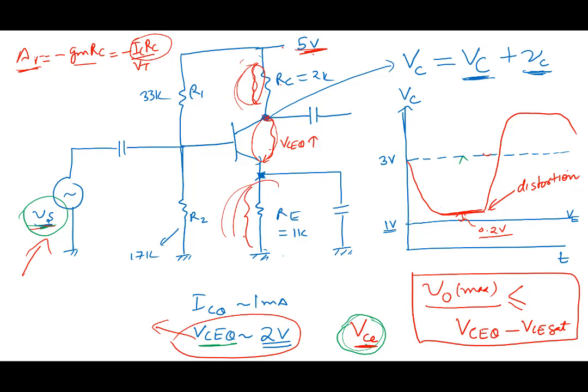Now what is this drop deciding? There's a drop here also. This drop is deciding IE. Why can't I make it smaller and smaller? Make this drop smaller. Right now, remember, we put R equal to 1K and this we put at 1 volt. Why not make it half volt? Very small. This point actually decides the stability, beta stability.